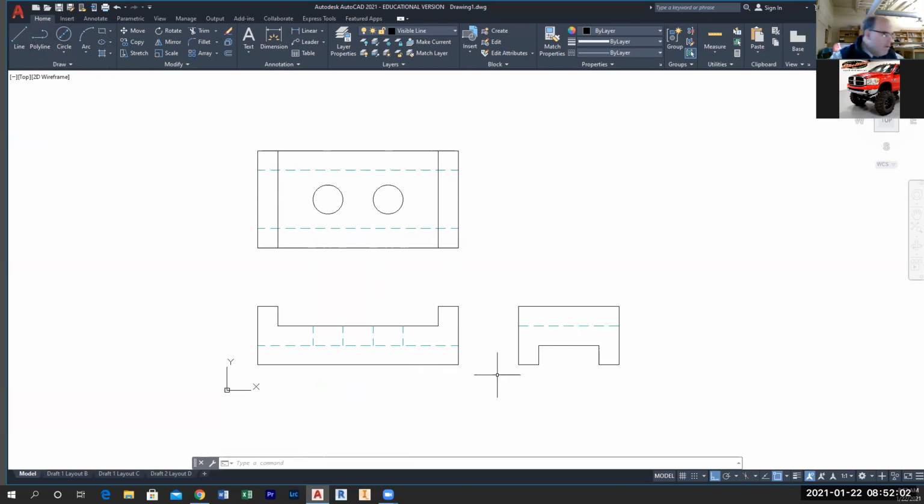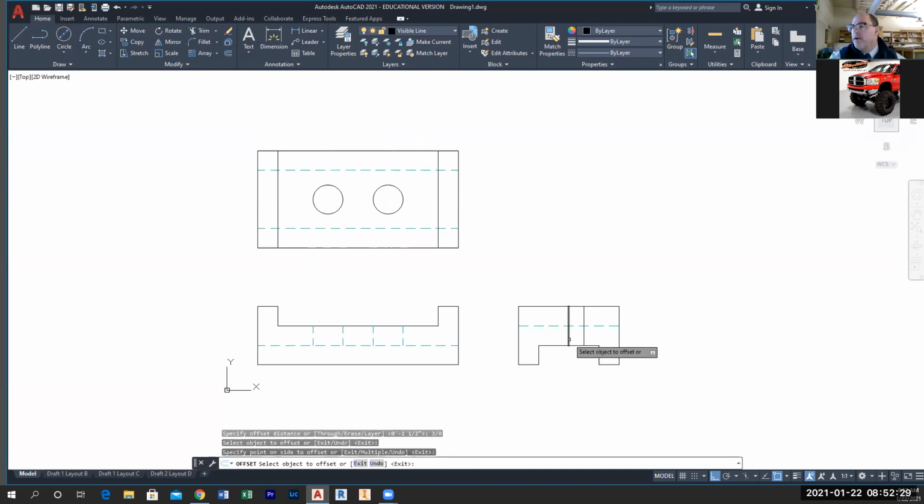Okay. I know this is in the center of this object. It says 1 1/4, 1 1/4, 1 1/4 is 2 1/2. So it's in the center. Okay. So if I draw a line, there's my midpoint. Boom. There's my midpoint. That's going to be the center. Now I'm going to offset this, whatever the size of my hole is, 3/4. So I'm going to offset what? 3/8 one way or the other, right? So let's just go offset 3/8, enter. And I go here and I go here. Okay. And then I'm going to go ahead and trim. I'm going to trim this thing. No, I don't want to trim that. Let me back up.